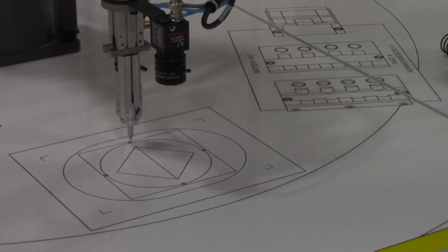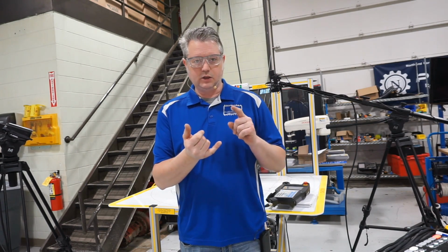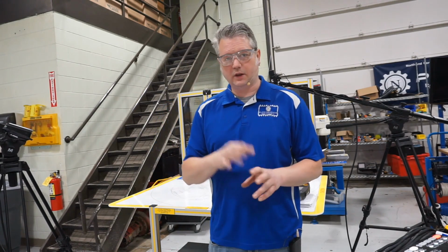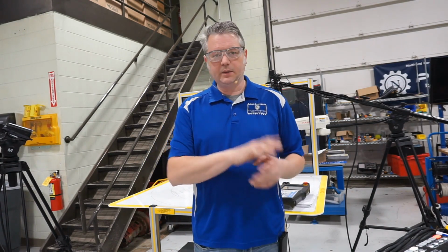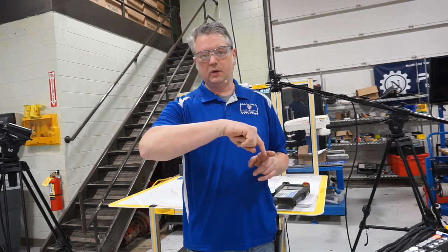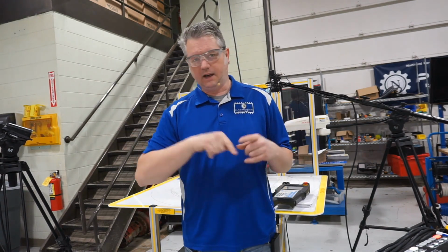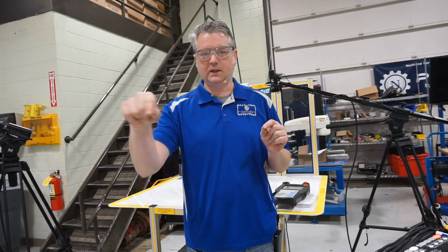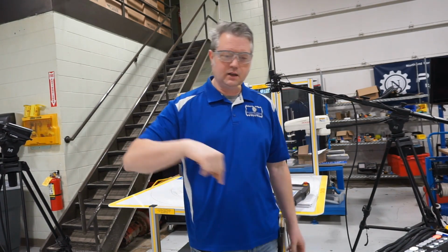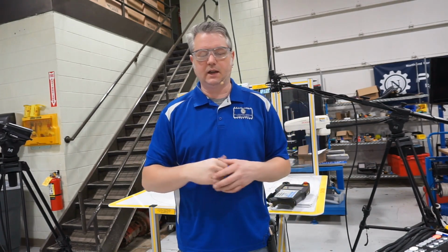Very good. So those are some of the commands that we can use to create different joint motion control instructions. We saw the difference between joint style moves, linear moves, and circular moves. So those are the three main types of moves that we can have with the robot. And we learned a little bit about the differences: joint moves are going to take the fastest way to get there, and it's not a straight line. Linear motions will be a straight line from one point to the next, and arcs are a little bit funny to program. They require us to use a few different points, and you saw how that was done.